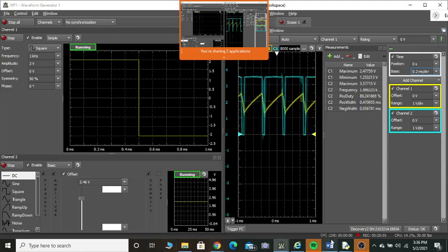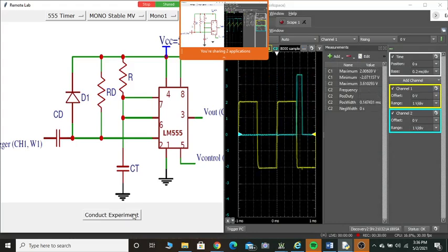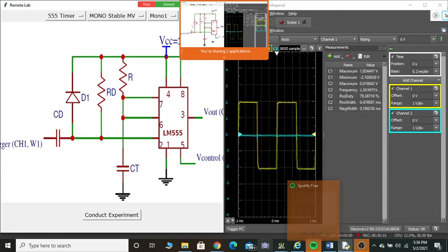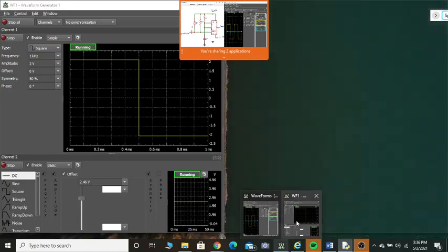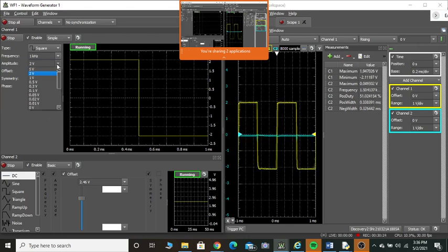So I had to go to this and then run this. If I run, can you see now you have the input voltage coming, but the output voltage is rarely coming. That is purely because my trigger signal is not going below VTL. Correct? What are the conditions for the monoshot to give the proper output? The trigger signal should go below VTL. So this 2 volt is not making it go below.